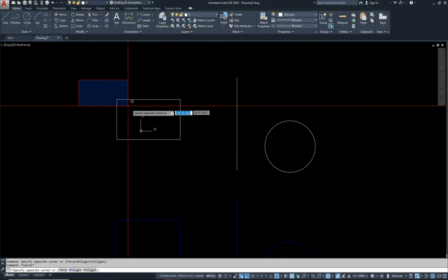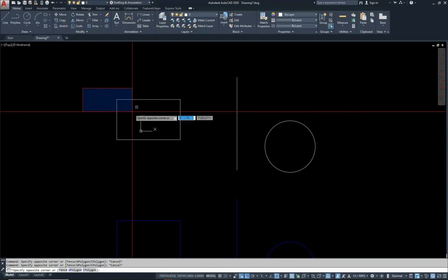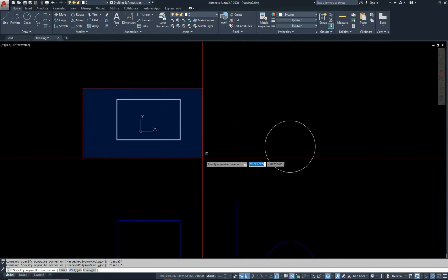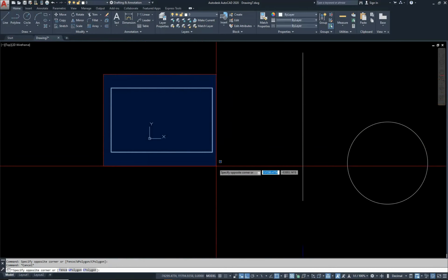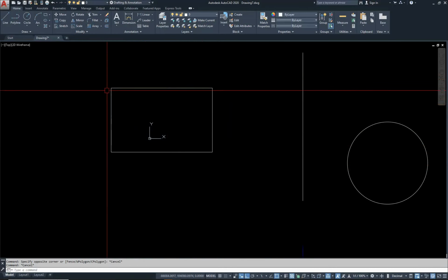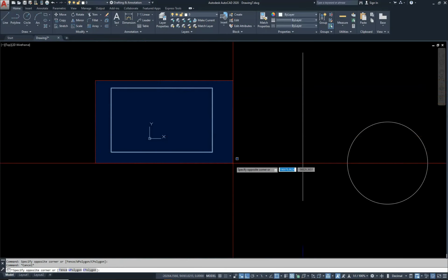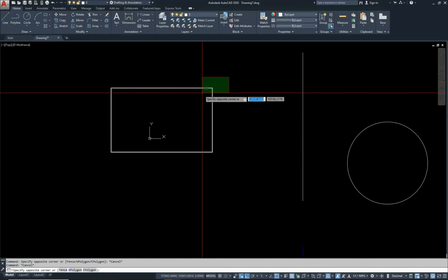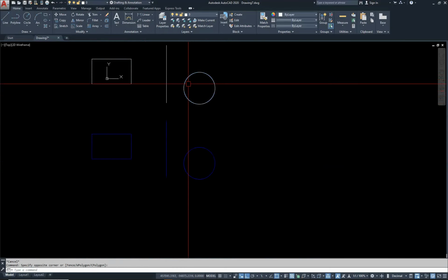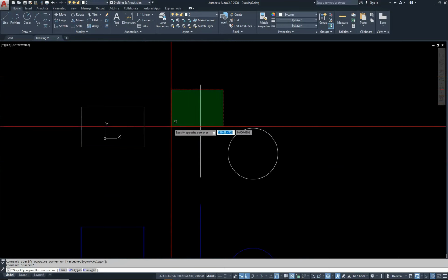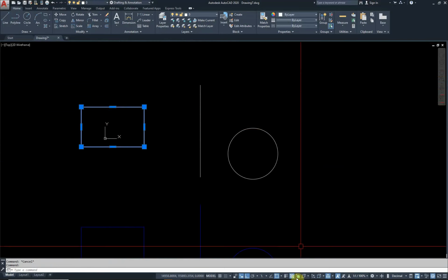But if I make this selection, which we can simply call the left selection, the object will be selected only when the whole object comes under our window. If I make it like this, no. If I do it like this, no. It won't select it completely. But like this, we can just make a small selection and it will go. In most cases we will use this kind of selection. And the third way, just click on the object and it will be selected.